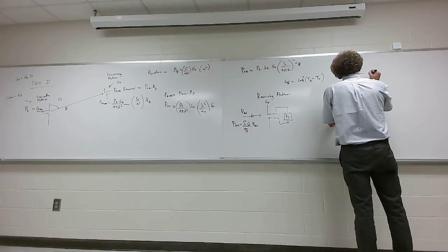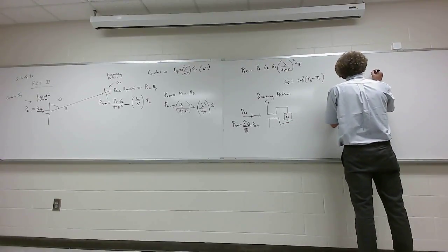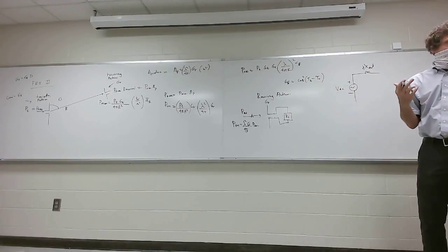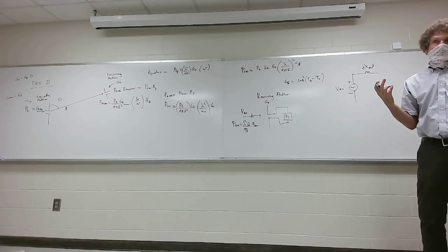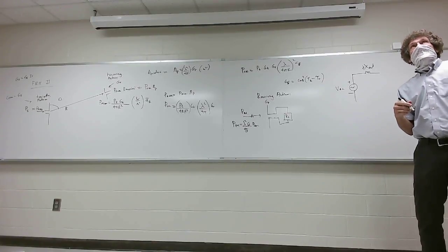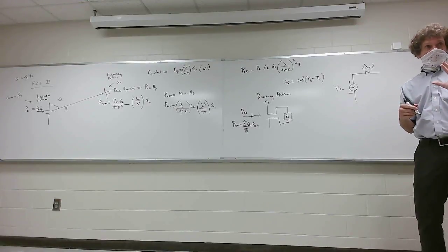Now, the antenna has some antenna impedance. So it's going to have some jX of the antenna. That's going to be the reactive component. Like with a half-wave dipole, it's what, 73.2 ohms is the real part of the antenna impedance, but then the imaginary is j42.5.